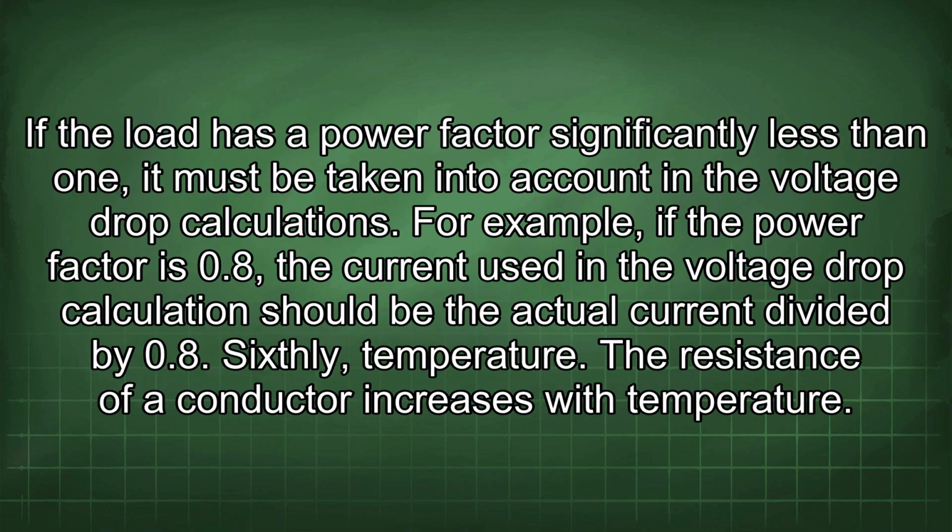If the load has a power factor significantly less than 1, it must be taken into account in the voltage drop calculations. For example, if the power factor is 0.8, the current used in the voltage drop calculation should be the actual current divided by 0.8.